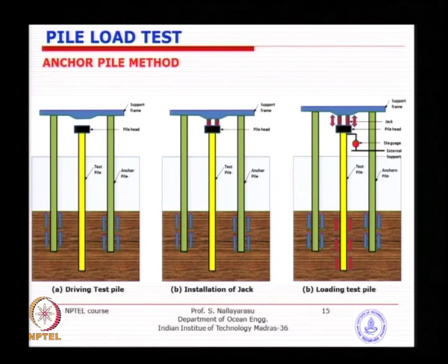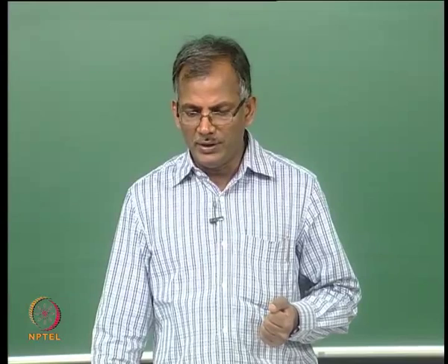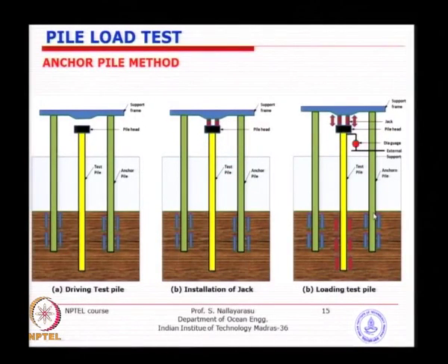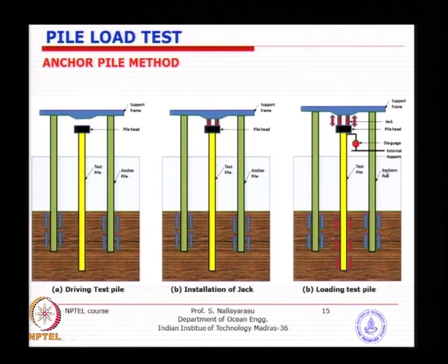This is a welded connection. So, always this anchor pile will be under tension. You need to have sufficient capacity of the anchor piles, so that means if you are testing 3000 tons here, each one of them will have to take a quarter of that and be designed with adequate penetration, because it is only tension.